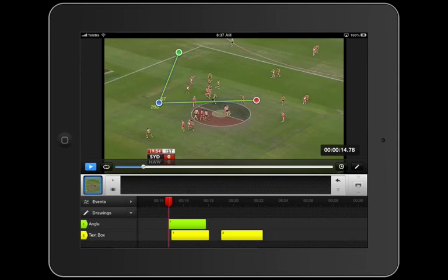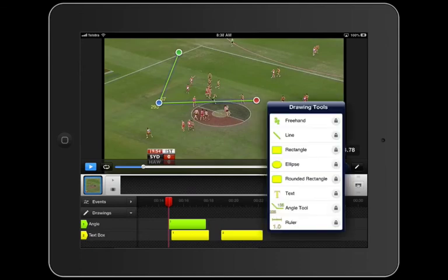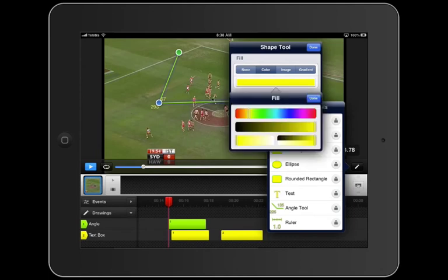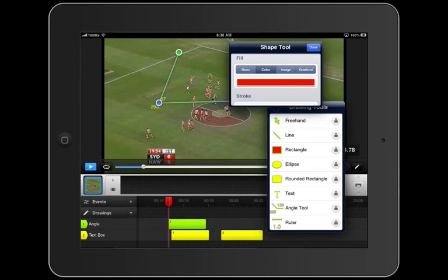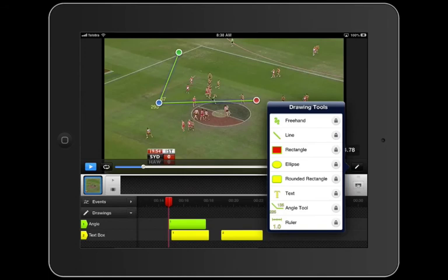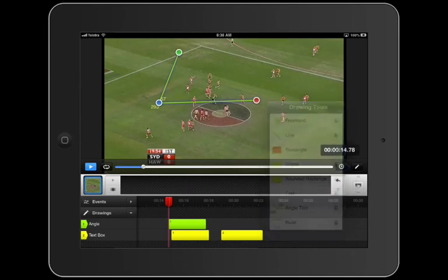Something about the inspector here that you may not run across is you can set these for the project, and you can set the properties, I mean to say, for each of these tools. And every time you use that tool, that property will be chosen. So let's change this to red because I want all of my rectangles to be red. And you'll see there that next to rectangle, that's now red. So the next time I grab that tool, that property will be remembered.